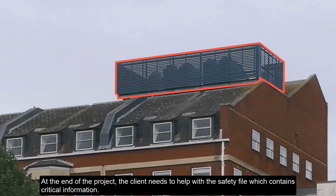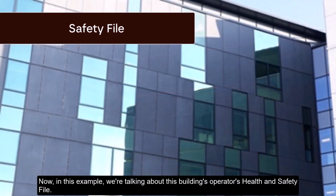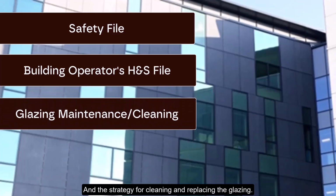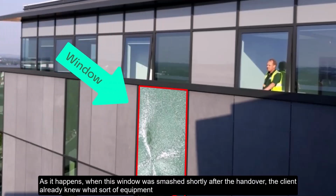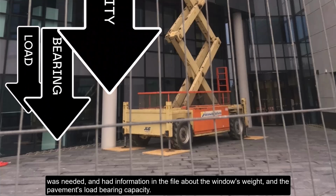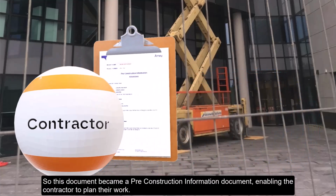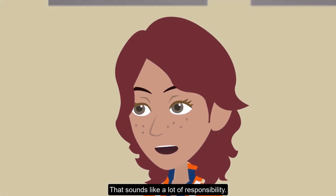At the end of the project, the client needs to help with the safety file, which contains critical information. Now in this example, we're talking about this building's operator's health and safety file and the strategy for cleaning and replacing the glazing. As it happens, when this window was smashed shortly after the handover, the client already knew what sort of equipment was needed and had information in the file about the window's weight and the pavement's load-bearing capacity. This information was provided to the contractor, so this document became a pre-construction information document, enabling the contractor to plan their work.